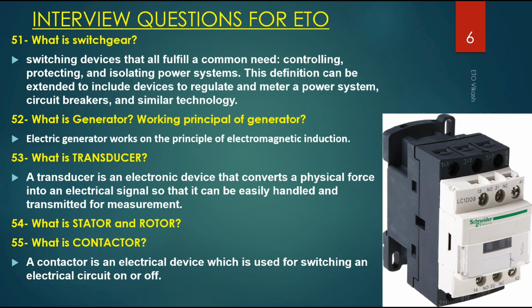So what is switchgear? Switchgear is nothing but a device used for controlling, protecting, and isolating the power system. It is a combination of circuit breakers, which we call MCB, MCCB, ELCB, VCB, ACB, and relays, and the metering devices like isolating transformer, CTPT. All this comes under switchgear.